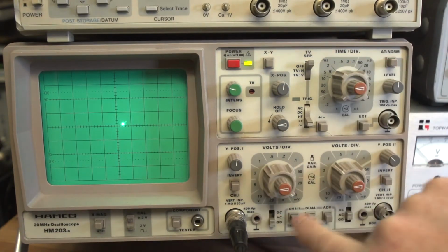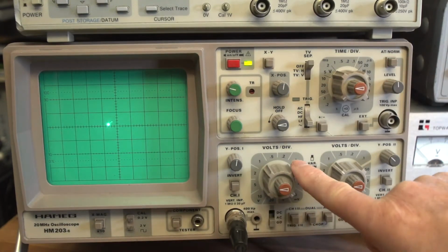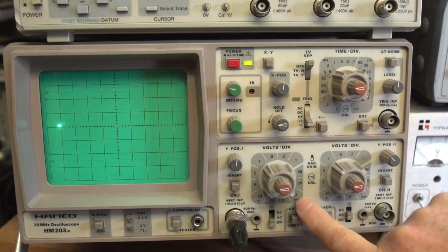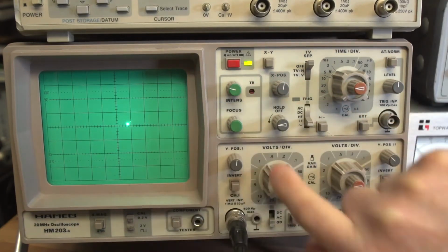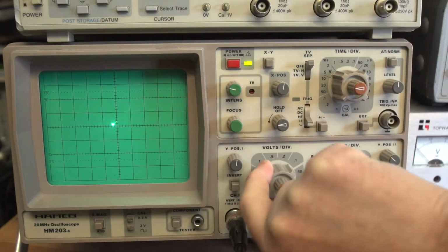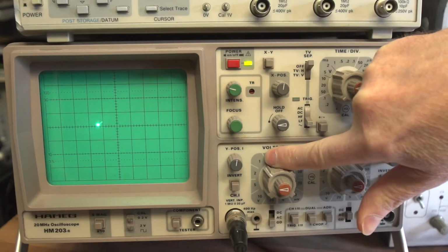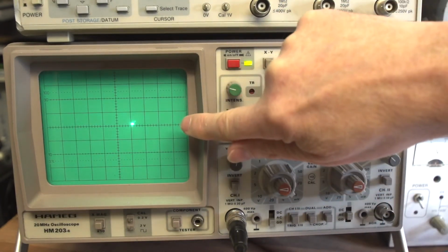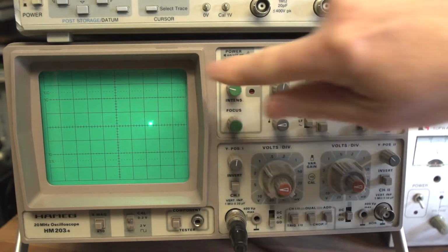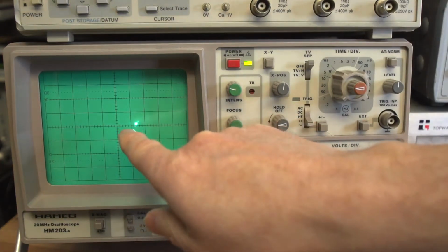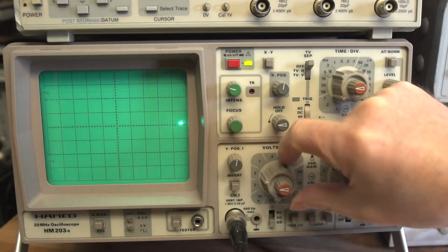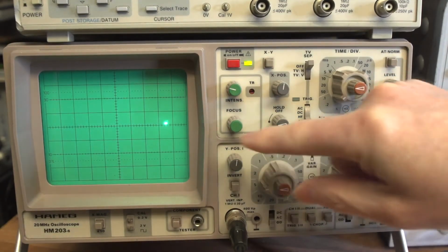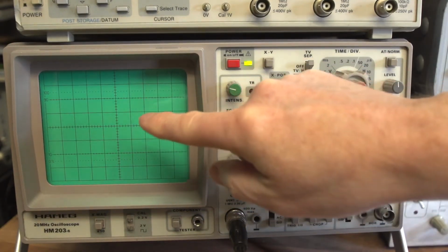But the Y, as I was saying earlier, is for the sensitivity of the scope, and at the moment it's taking 10 millivolts, which is what we were showing with the microphone earlier, to move it 1 centimeter. And you can adjust it. If I turn it up to here, this is now 1 volt per division, per centimeter graticule position. So it takes a volt to move that dot up a box or down a box. That's 2 volts. That's 5 volts. So now it takes 5 volts to move the dot positive or negative.